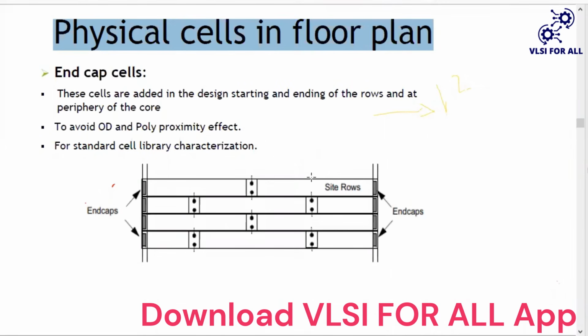In your ongoing project we can explain this in more depth, but here I am explaining how double heighted standard cells are used. The functionality, the logical connection and the physical connection will be the same, but for timing purposes, to store a value or for clock purposes, the timing values will be specified, with some spine related cells. Remember, spine is the main topic at the CTS stage.